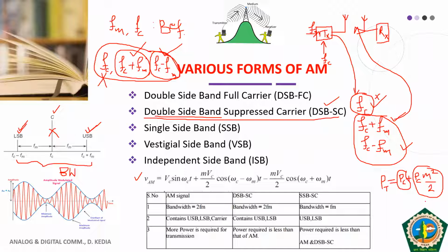If you analyze this carefully, the total power present in the carrier component is approximately 67%, and the total power present in these two sidebands is just 33%. So after using the carrier, we have got two higher frequencies, and our information signal is present in those sidebands only. In the carrier FC, we do not have anything.